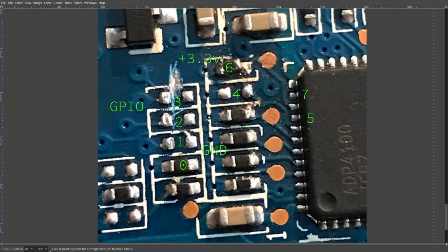And not having VID 5 means you're basically limited to VIDs 1.2 volts and below and 1.4 volts up as your only real easily achievable VIDs. So you'd have to use a feedback mod to get 1.3 anything. So in that case, you'd set your VID to 1.2, use that up to about 1.3 with your feedback mod, and if you have to go higher, you have to change your VID all the way up to 1.4, and then you use your feedback mod from there.